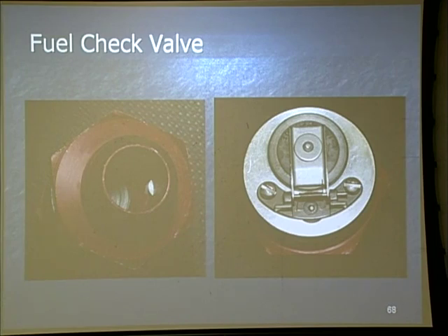But for the most part, you'll notice all of these check valves tell you which direction they're operating. What it does is prevent fuel from going backwards in through the tank, because again, we're talking low pressure versus high pressure. It's going to want to go through the path of least resistance, which, based on gravity taking it down, plus pressure, would be back over to the other main tank.